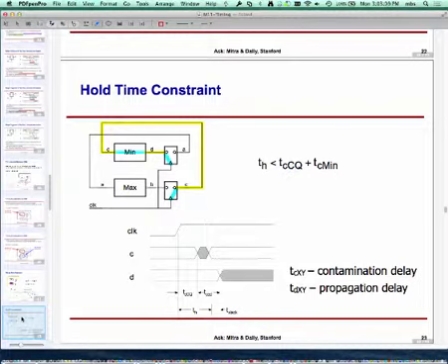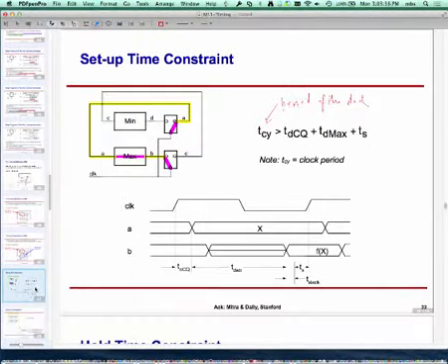Did you say if you made the hold time negative, the whole process will be slower? Right, because if you think about it, if hold time is negative, then setup time... If you think about it like a stability window, if it was about my clock edge, it's fine. Now making the hold time negative means I'm moving it before the clock edge. So the setup time will become more positive. And if the setup time becomes more positive, then by our previous equation, this is going up, which means TCY will generally have to go up.